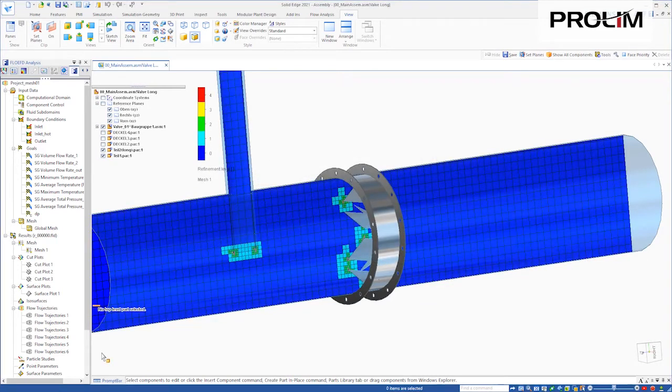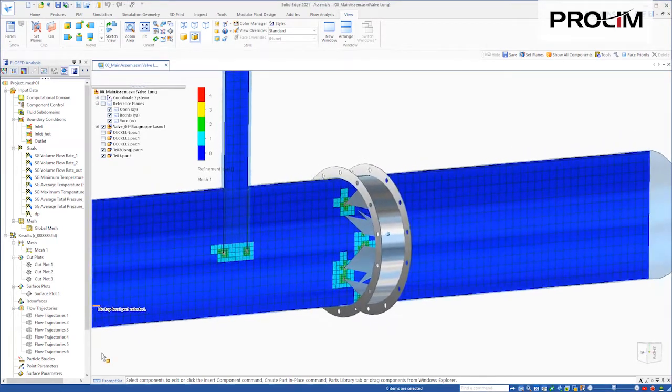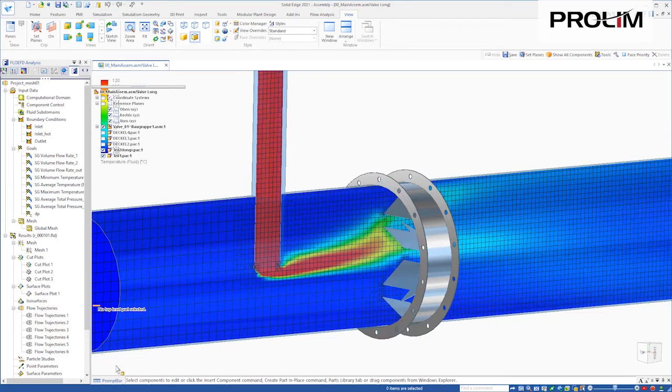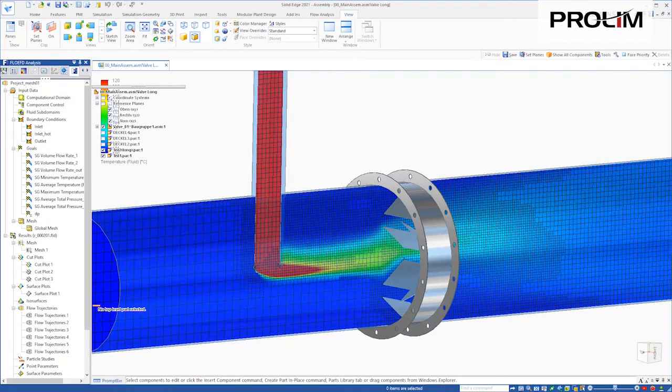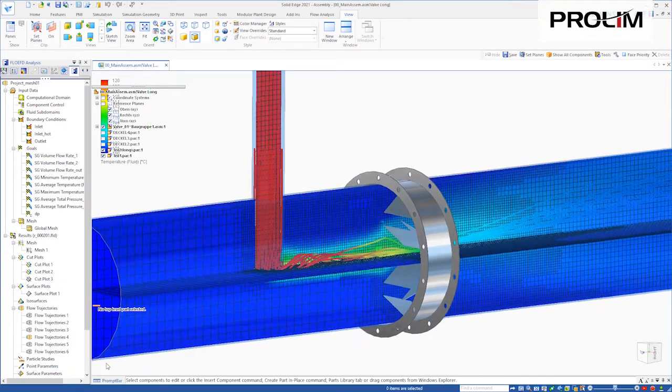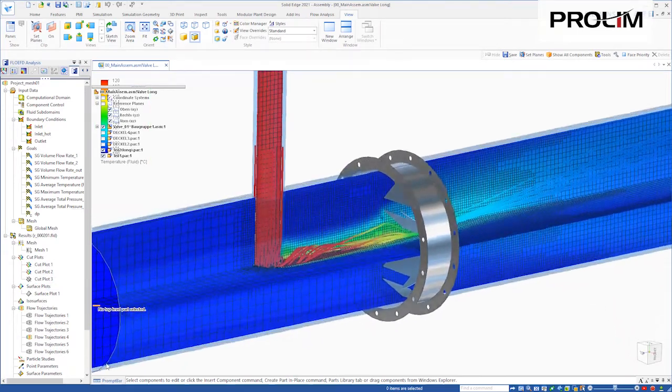This plot shows the initial mesh with the geometrical refinement only, for example at the blades in the valve and the hot gas inlet pipe. Now we can see the first and second solution adaptive refinement, which is based on the gradients, for example in regions with high temperature gradients and recirculation areas. Different cut plots show several regions of the results and the refinement.